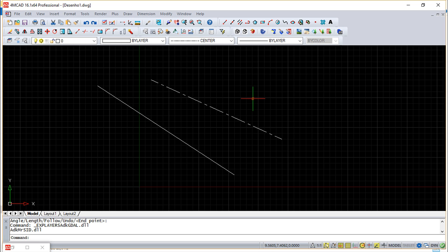Now the idea is to create or to name other line types, your own patterns, okay? So this is to tell you that in addition to the predefined line types you have in the program, you can create new ones, and these new ones can be both complex or simple. As I said when we started, let me show how to create a simple one.